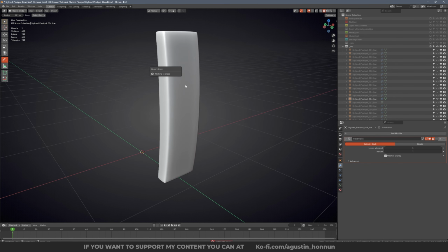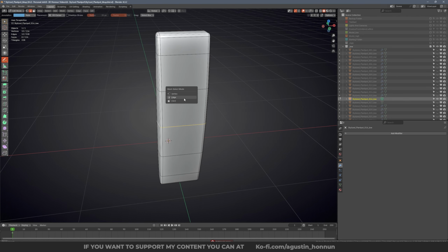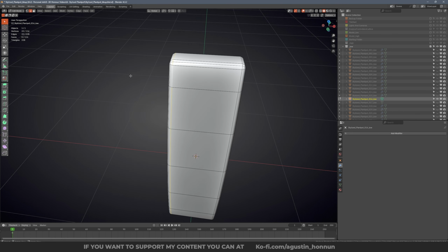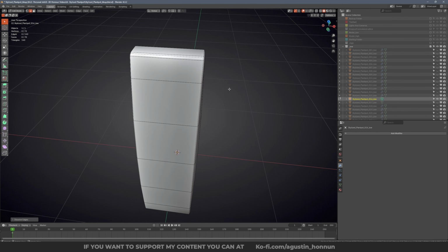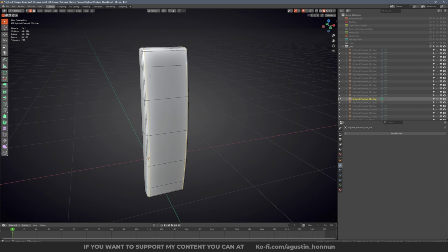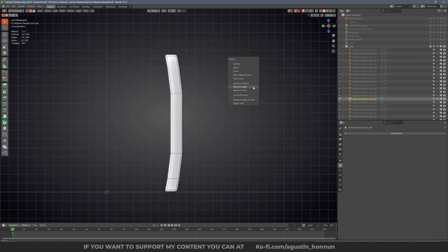model. So this time I'm going to remove the subdivision modifier, then enter edit mode, and we can start optimizing this. You need to remove edges that won't affect the silhouette also. For example, if we remove this one, this will happen. That will affect the geometry a lot here.